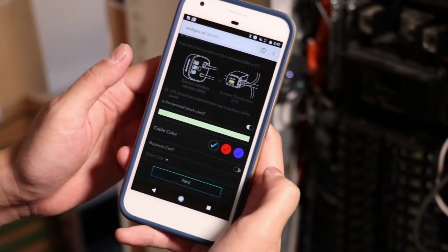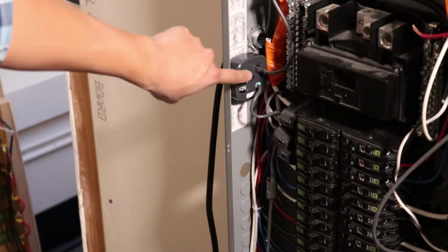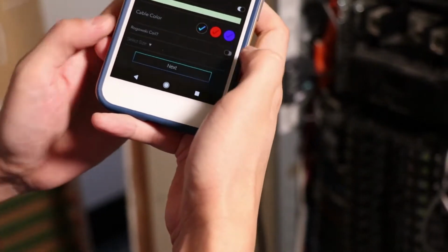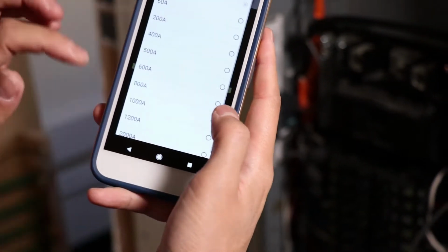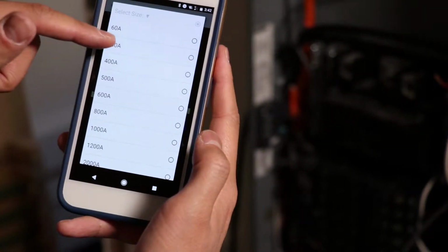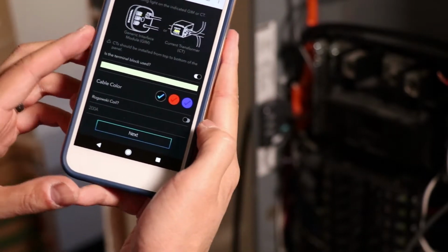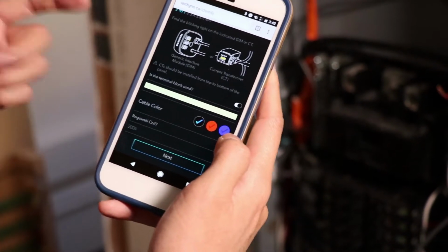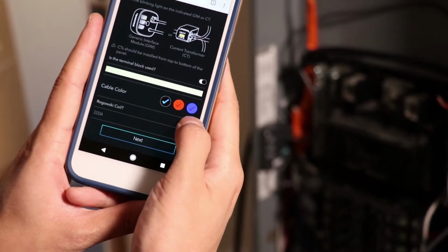It's really important to note which port of the generic interface module you're on, because the phase association is very important for making sure the power calculations are correct. Because the generic interface module takes many different sizes of current transformers, you can select what size of CT you use from the array that we provide. And there's a particular option for Rogowski coil, because the Rogowski coil power calculation is done differently than the split core ferrite. So in this case, we're not using Rogowski coil, so I'm going to leave that option off.